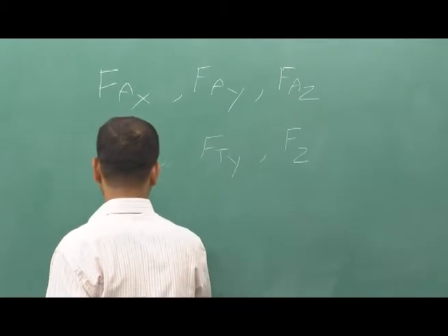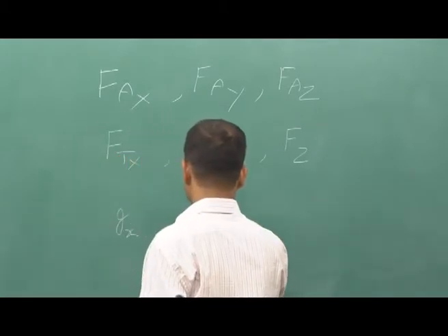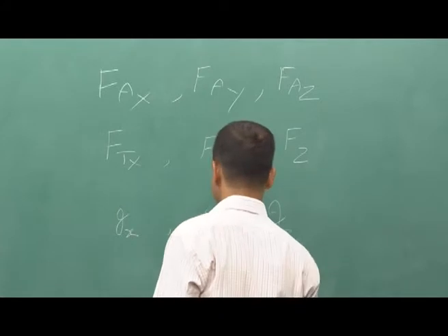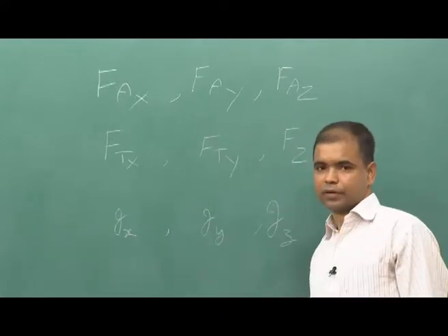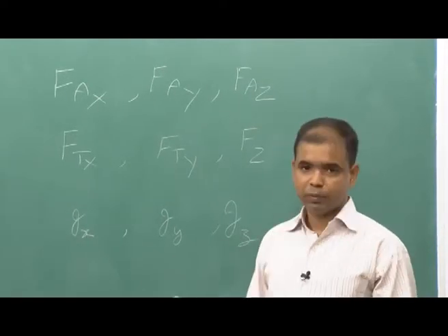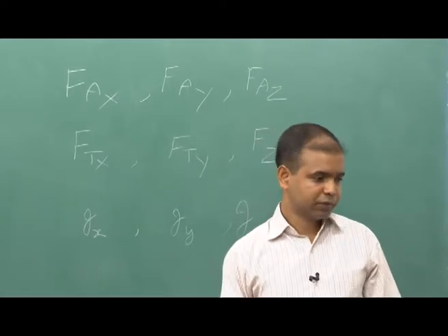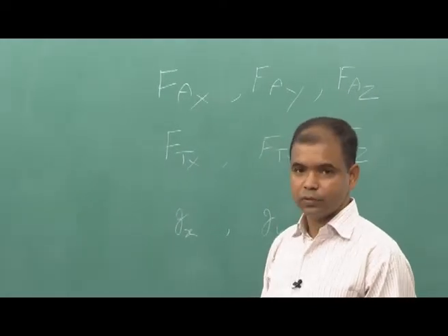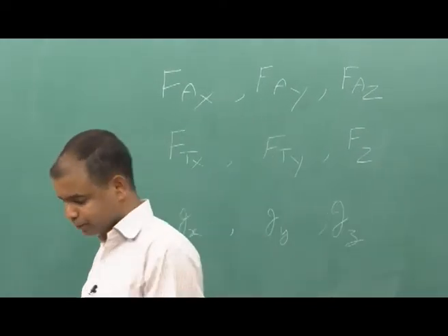You know the orientation and mass. So, using the gx, gy and gz, the gravity components in x, y and z direction, you can calculate the gravitational force acting on the aircraft in all three axes. Now, you will be using these forces and the equations of motion that we have derived in the previous classes, and we will see how we can find the trajectory of the aircraft. In previous classes, we have derived 6 degree of freedom equations of motion, and we have two sets of equations, each set 3 equations.